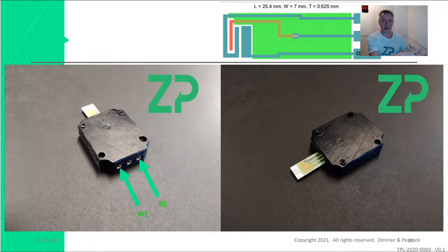I show it like that because a lot of people have potentiostats. You don't, strictly speaking, need a potentiostat to measure an ion selective electrode. You just need a high impedance voltmeter. But those in labs often have potentiostats, so you need one of these connectors.